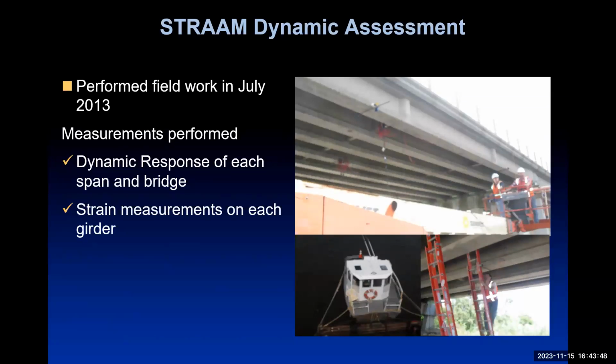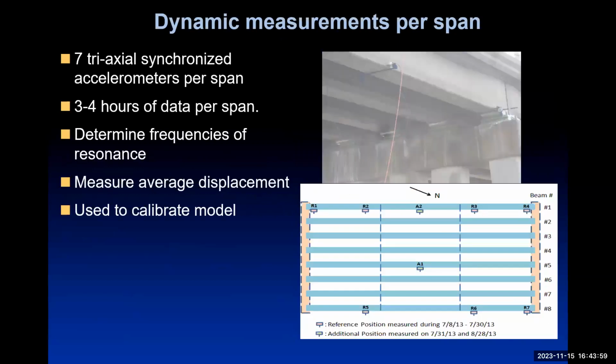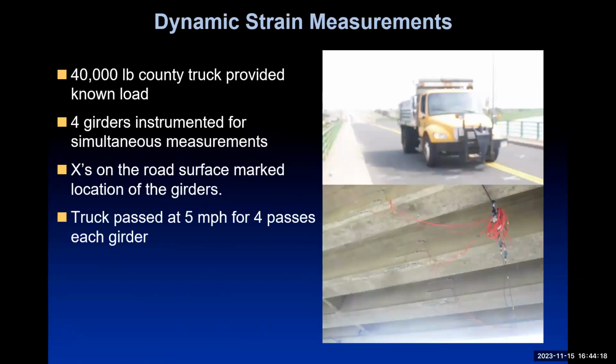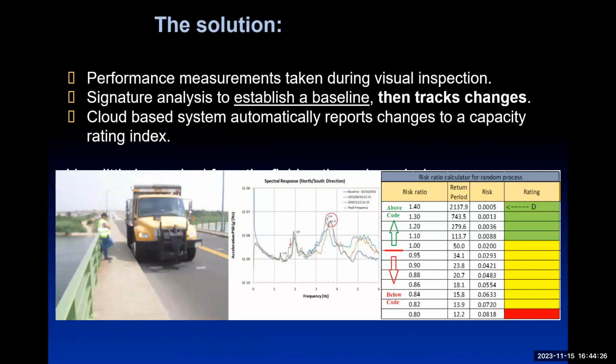Then there is an ordinary concrete bridge. We looked at this one because of rusting occurring, and we're having a look to see if the performance was okay. Well, in practice, it gave us some very good information. We found natural frequencies, and we used a finite element model, partial finite element model, to simulate what the characteristic was. And then we used a truck which was laden, and we measured what the response of the structure was.